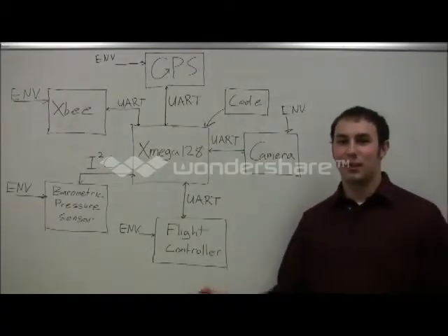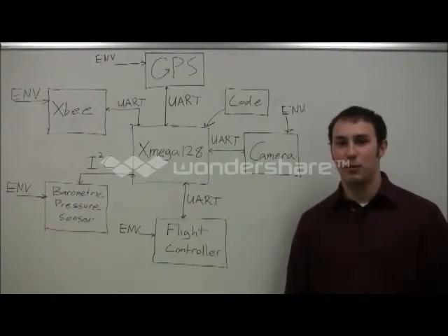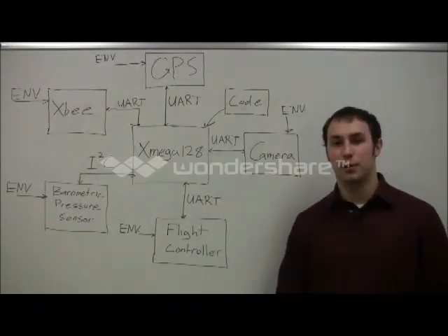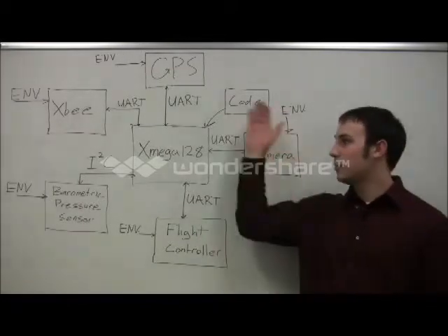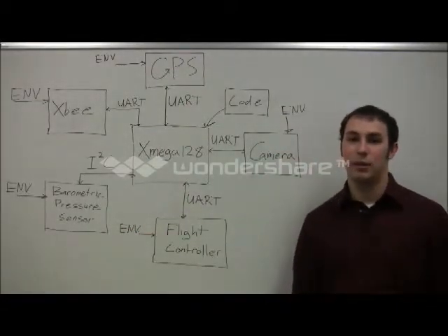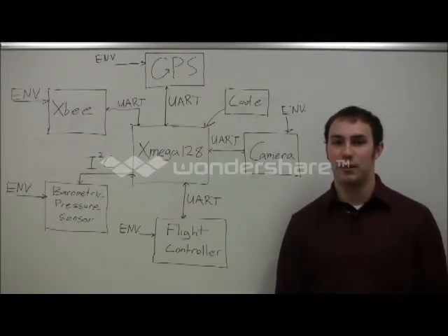This is the block diagram for the main processor block of the UAV project. First, it uses an Atmel XMEGA128 microcontroller to process all the data from these 4 separate modules, as well as send commands to the flight controller block that will be discussed by Brandon Fry in the next portion of this video.